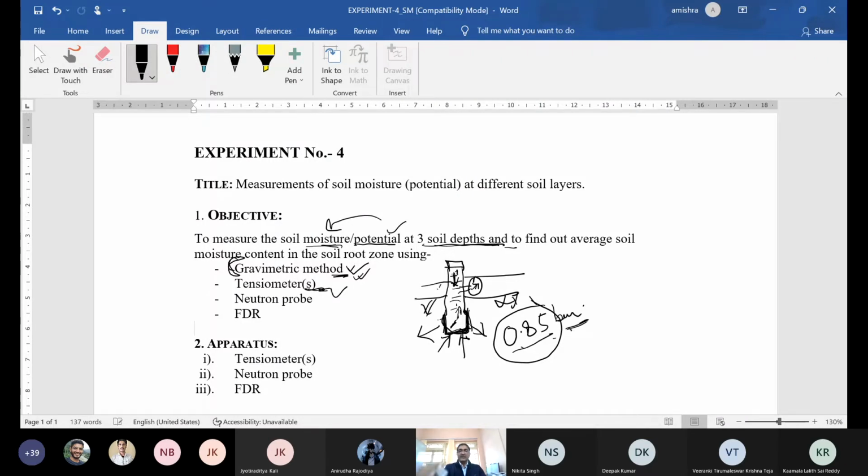These are not suitable for clay soils, the reason being clay soils develop cracks, and through cracks the soil compactness around this cup is reduced, and they will not work. In that sense, porous cups are not very suitable in black soils where cracks are developed.